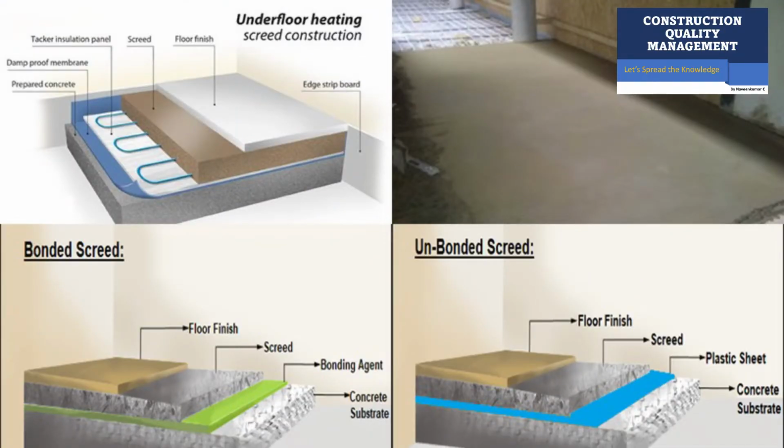The thermal coils will be placed inside the screed, and it will be sandwiched with the top floor screed and the mother slab. During extreme cold weather, we can activate these coils to make the floor warm. So the floating screeds are majorly used for such particular accommodations.